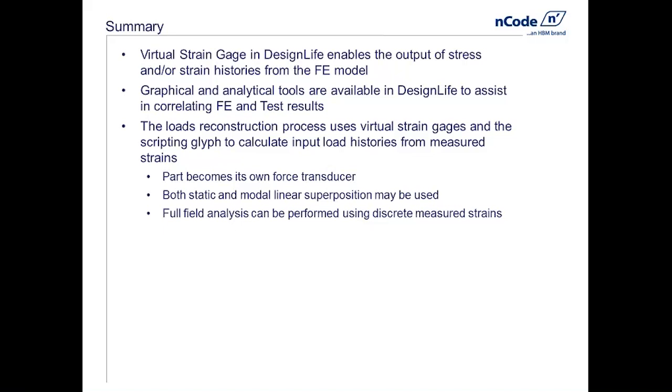And with this, again, I've turned my part into its own force transducer. Any analysis that I do that is using linear superposition, again, that could be modal dynamic or it could be linear static, can be used in this process. But the key is I am actually superimposing stress states to do this, so they have to be linear combinations. But when I get done, I now have the required loads or modal coordinates that I could apply to my FE model and do a full field fatigue solution.